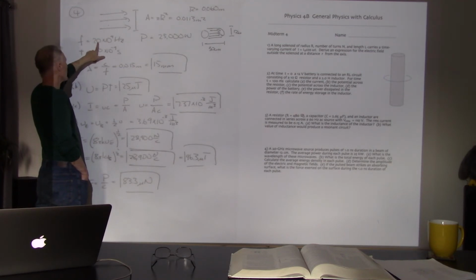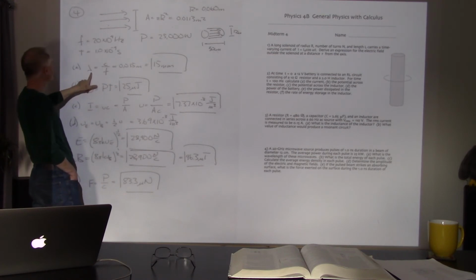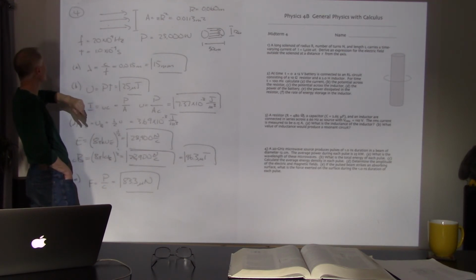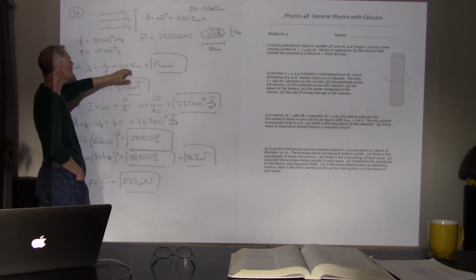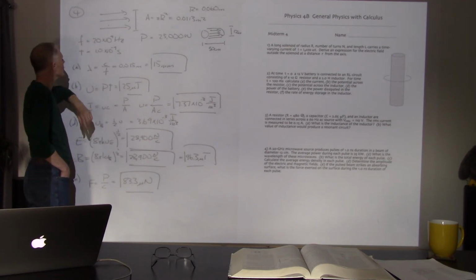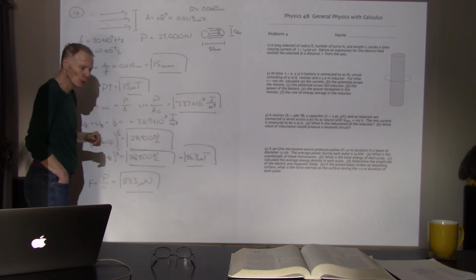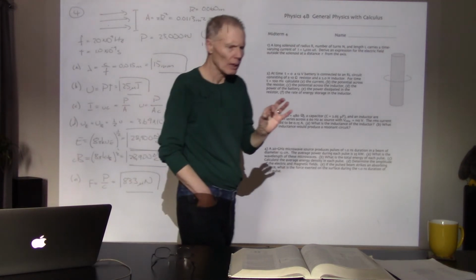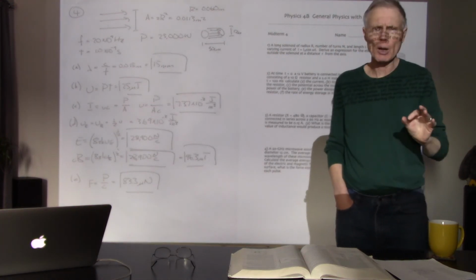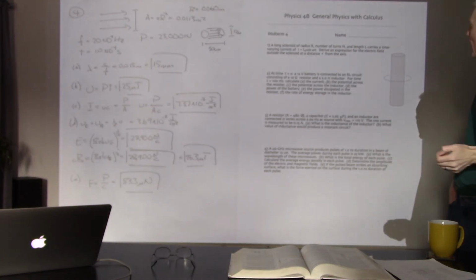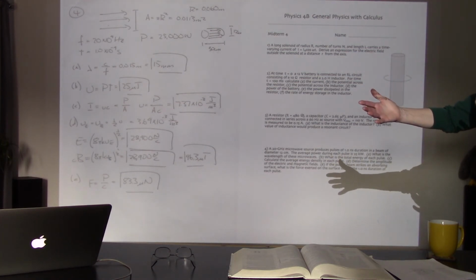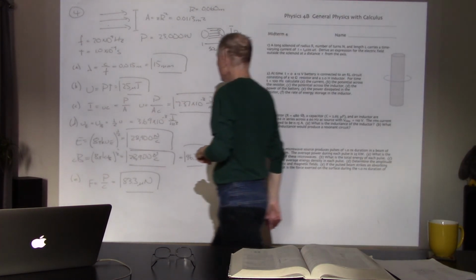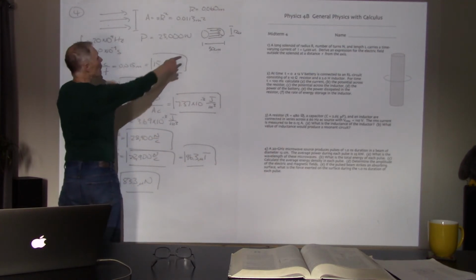The frequency is 20 gigahertz, so I've got the gigas in there, and from that I was able to calculate the wavelength by taking c over frequency, and what I'm seeing is that this is about 15 millimeters as a wavelength. So the wavelength is pretty short. Electromagnetic fields propagate at the speed of light, and in 1 nanosecond they only travel about 30 centimeters.